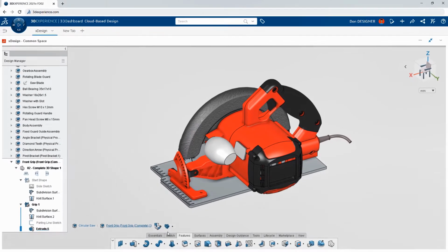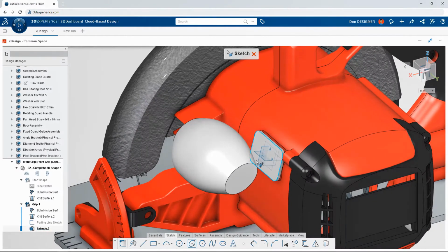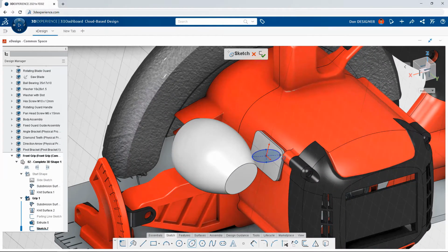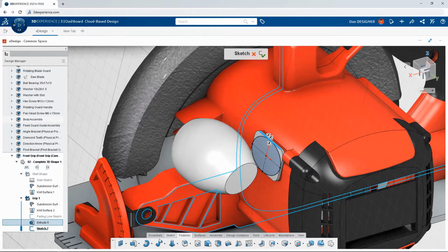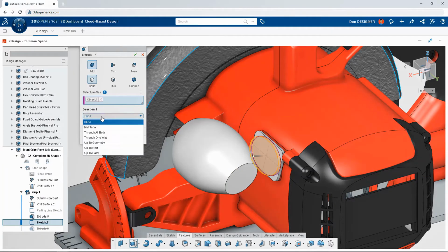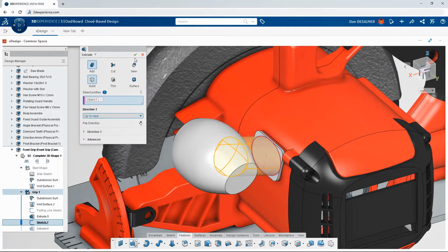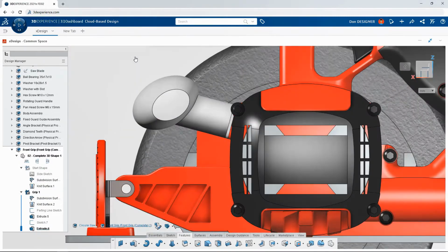Sketch ellipses include construction lines, making them easier to orient. For example, Don can snap the quadrants of the ellipse to the midpoints of the external model edges, or he can also click on both the point and the edge, opting to create the same relationship in the pop-up menu. These relations will fully define the sketch. While extruding the feature, a preview is displayed, making it easy to confirm the correct end condition has been applied.